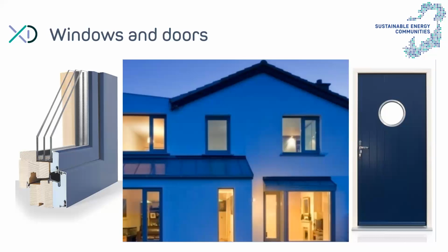There's another option, which could be to leave the window frame in place, right? And then replace the glazing with a high quality double glazing. There are now slimline double glazing units which have a very good level of performance, and which can be placed as a replacement to existing bad quality double glazing or even single glazing, while retaining the existing frame. Sometimes the frames are good quality timber frames. In period houses, for example, retaining them would be an important feature,